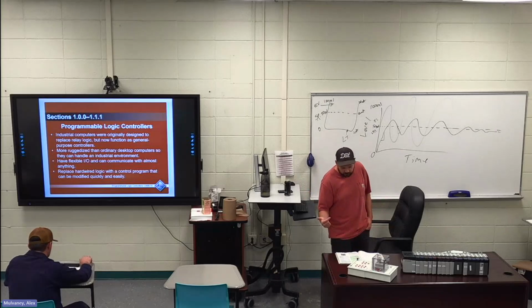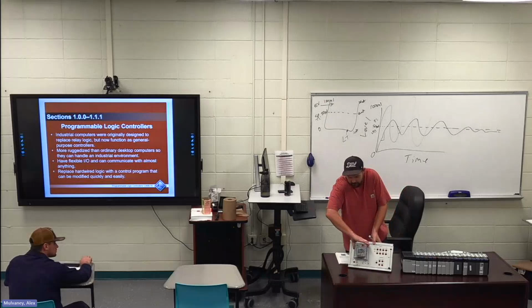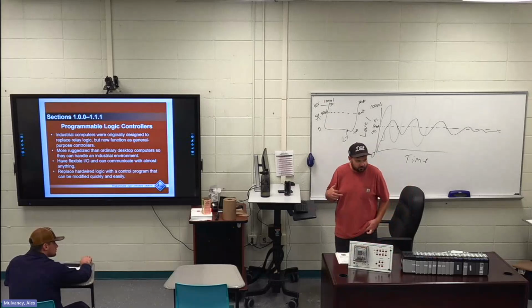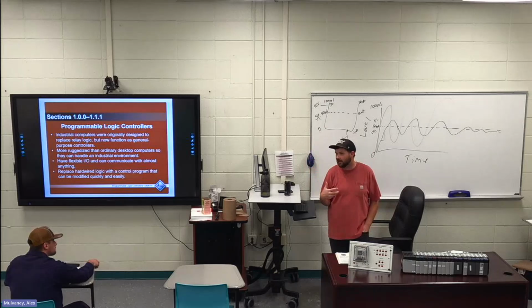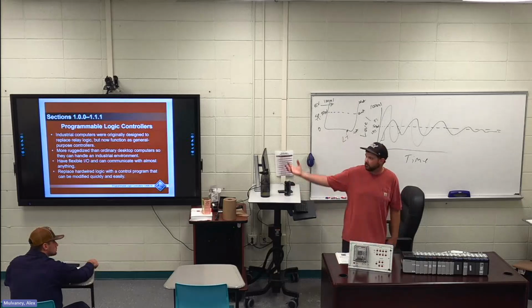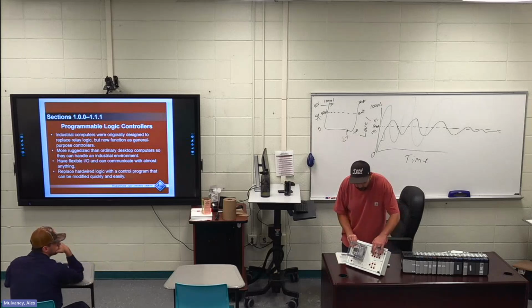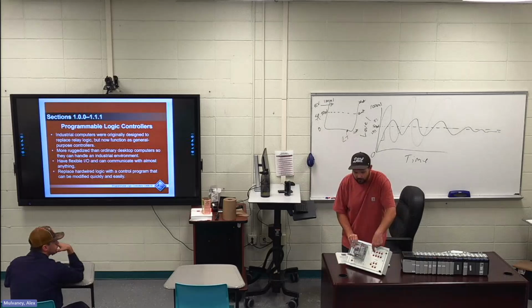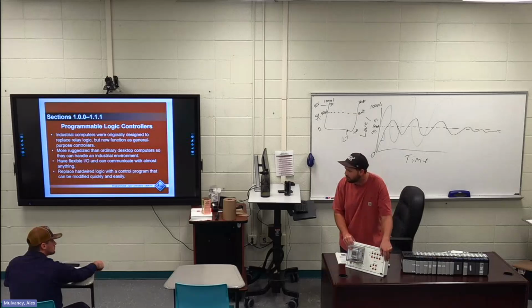Input, output. There are going to be inputs and outputs on all the different types of PLCs. The two main types of inputs and outputs are digital and analog, right? So what would be a digital input? 1, 0. Ones and zeros. What's a device that is only ones and zeros? An on and off switch. If the lighting in this room were on a PLC, that switch would be an input. This is the back panel to the big motor control, so I have digital inputs 00 through 07. I can have a digital input right here saying input 1 is on or off, and that's a light switch. Then it talks to the brain of this and configures an output.